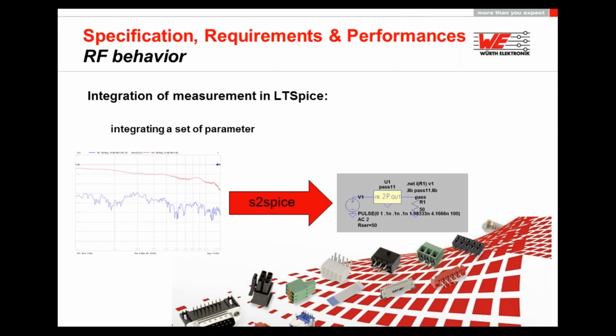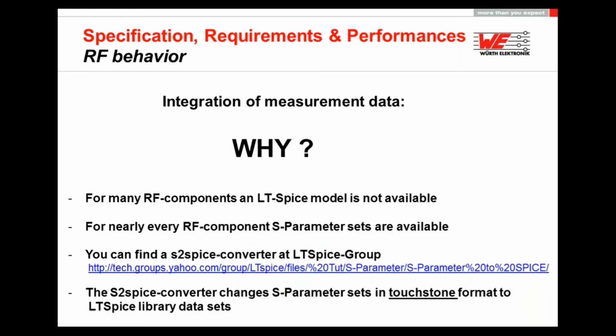Okay, so what we can see is that the USB 3.1 Type-C is really a connector where we are able to handle these higher data rates, even the third harmonic of the frequency that is needed. And we are also able to handle the higher power supply current that we need, and also the mechanical parameters, like, for example, 10K mating cycles.